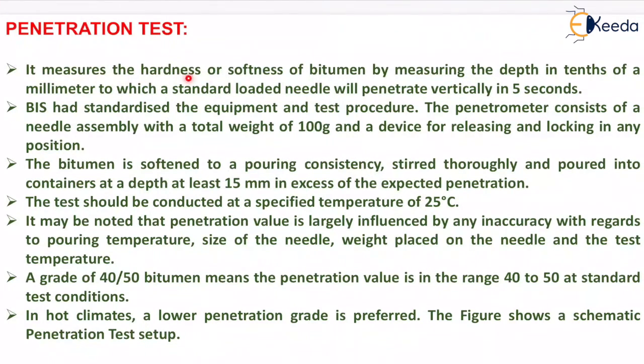It measures the hardness or softness of bitumen by measuring the depth in tenth of a millimeter to which a standard loaded needle will penetrate vertically in 5 seconds. Bureau of Indian Standards has standardized the equipment and test procedure.